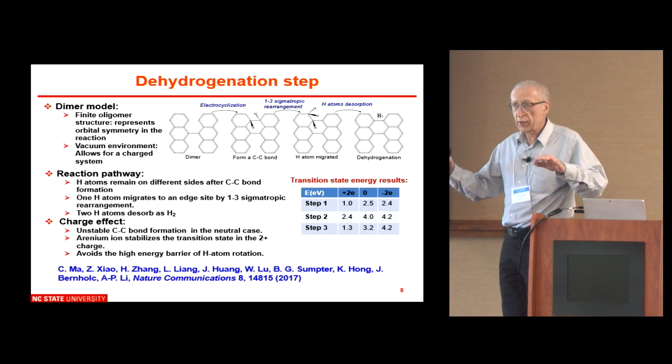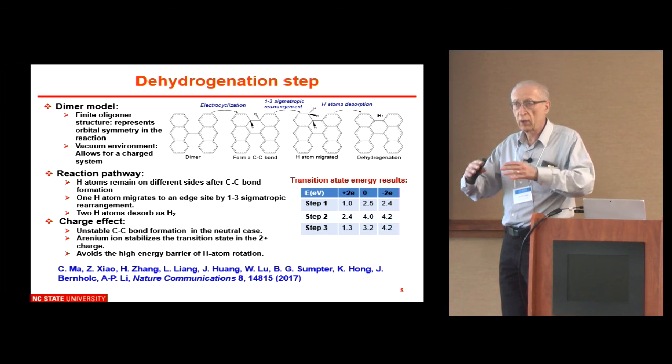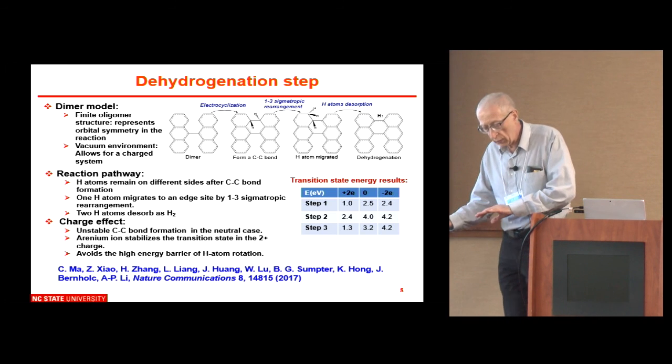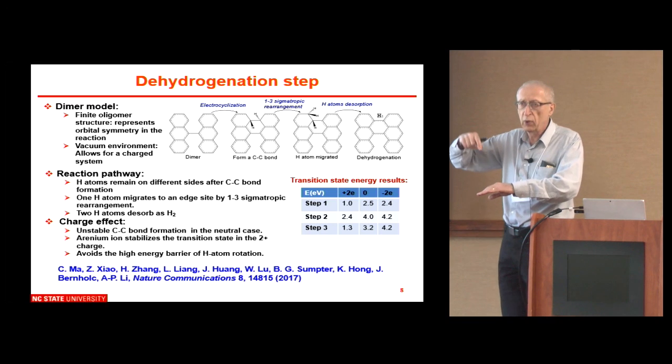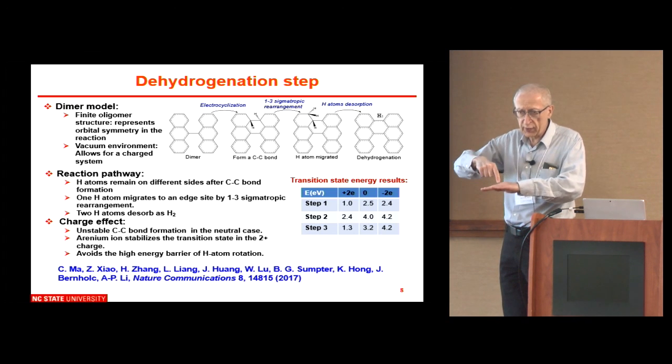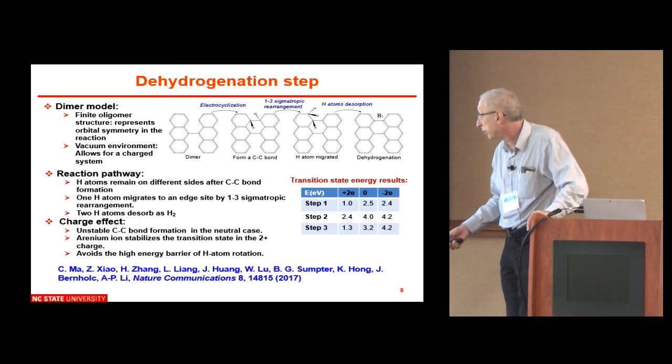on the substrate at a certain temperature, then keep it there without raising the temperature, and the transition to graphene nanoribbon does not occur, but one can then use an STM tip to give a pulse to the polymer at precisely that location, and then that's going to convert either fully to a nanoribbon or partially to a half nanoribbon, half polymer.